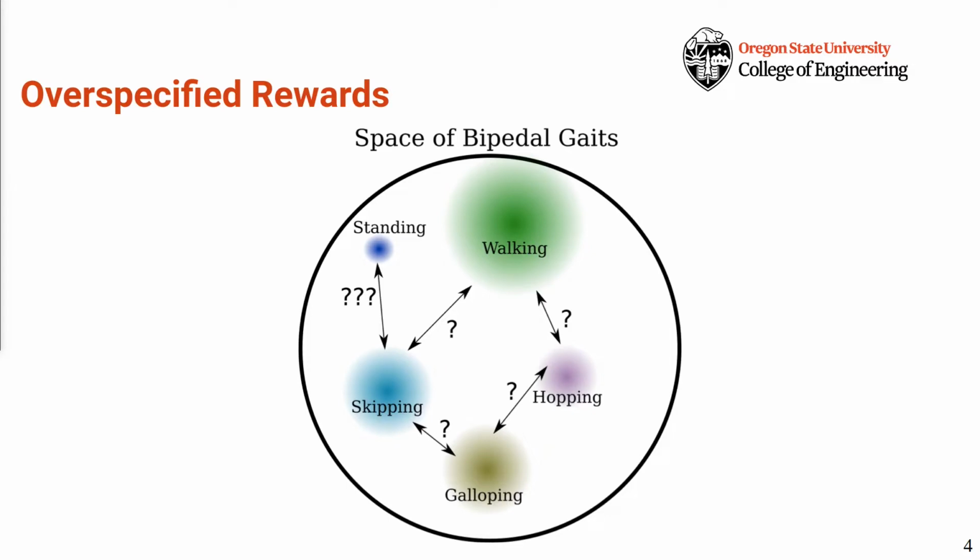There's also the question of switching gaits. Once you've learned a walking controller from a walking reference trajectory, can you somehow extend that to hopping? And say you have two reference trajectories, one hopping and one walking, how can you switch between them smoothly? These are questions for which there is no good answer if you are in the framework of reference trajectories.